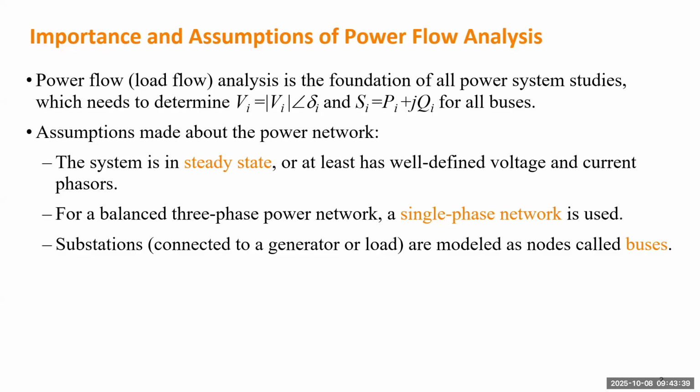They can have tens of circuit breakers, separate line by line, equipment by equipment. But in power flow analysis, we don't go into the detail of each substation. We treat a substation simply as a node, or a better word is bus. Bus means it can deliver power or receive power in many directions, so you can connect many lines to the same node. Think of a node as a dimensionless point, but that is not accurate. The bus itself in a power system can be another, smaller scale power system, but usually we call it a bus.